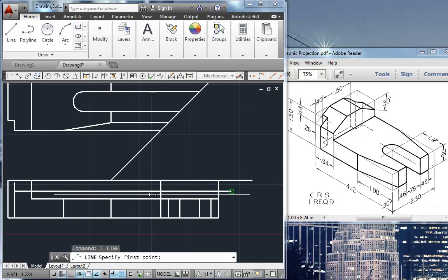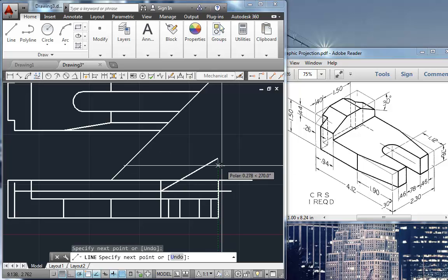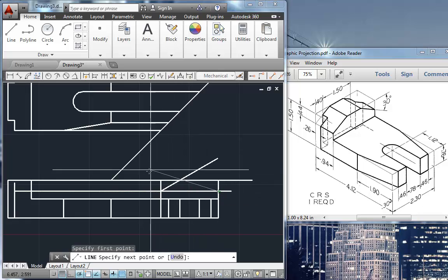So I'm going to do a line from here. That's this corner, by the way, 0.44 down. And we're going to go uphill at 30 degrees. So we're going to go angle 30, and there's that line. I'm going to do the same thing from this side, but now my angle is different. It's going to be 180 from here, 180 straight across, but I want to go up 30. That's clockwise, or negative. So 180 minus 30. So I'm going to go 150. Angle 150 right there.